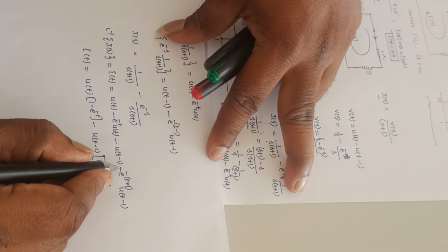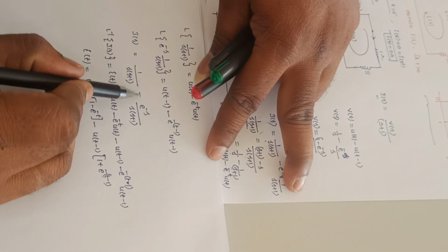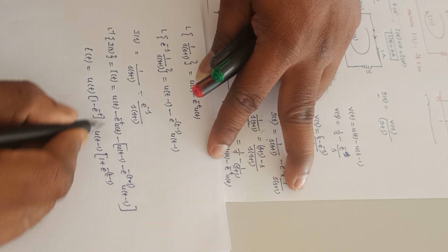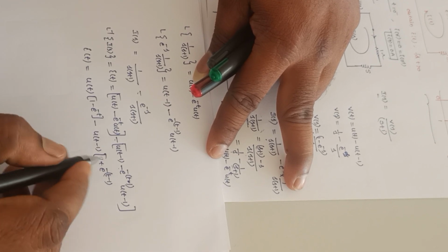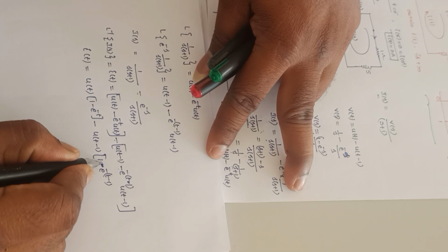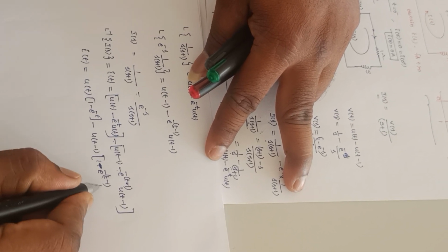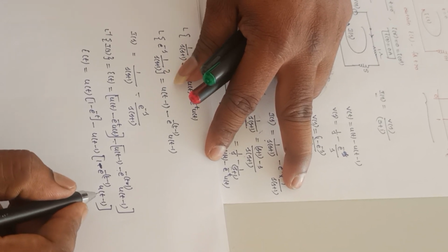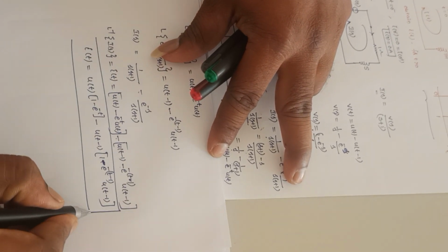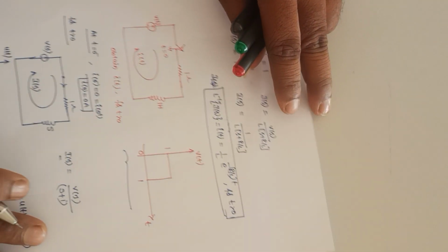So it is plus here, I think it is plus. Why? Because here it is a bracket, I forgot to place the bracket here. So minus into minus, it is plus. If I take the minus, so it is 1 minus, sorry, u of t minus 1 is common, e power minus t minus 1 into u of t minus 1. So this is the expression or response for this problem if this type of signal is applied as an excitation for this RL circuit.